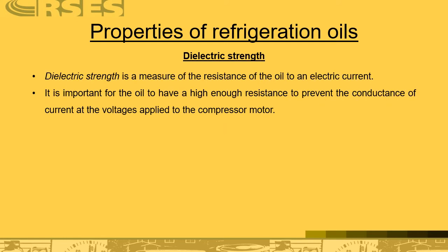Dielectric strength. Dielectric strength deals with the resistance of oil to electric current. It is important for the oil to have a high enough resistance to prevent the conductance of current and voltages applied to the compressor motor, such as in hermetic compressors.